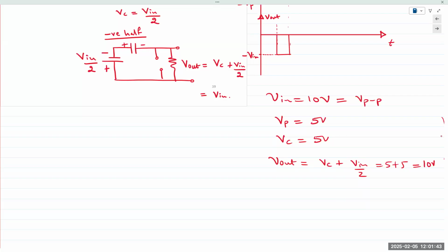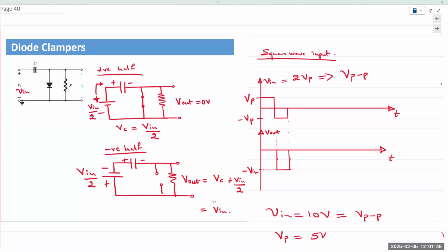Yes, when it's a short, the capacitor is charging. No. So when it's open, the time constant of the circuit, if this is R right here, time constant tau is R times C. When it's charging, it's RD, the diode resistance.